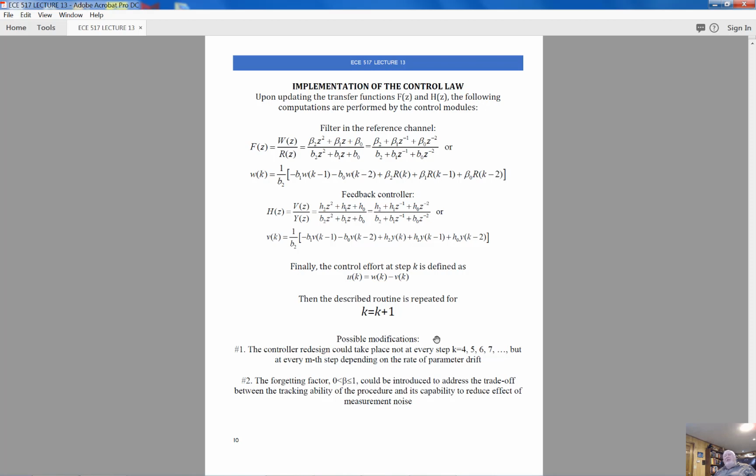So you will have an opportunity to implement the explicit self-tuning procedure in your take-home project, and you will get some additional experience with the use of self-tuning. I want to emphasize that we call this approach explicit self-tuning because it implies that we estimate unknown parameters of the control plant in the most explicit form.